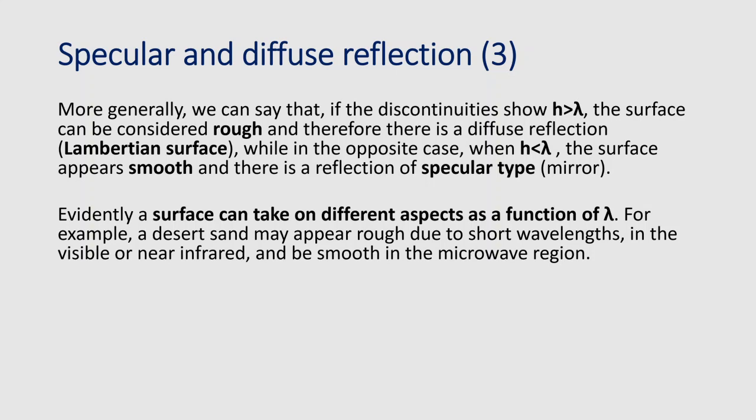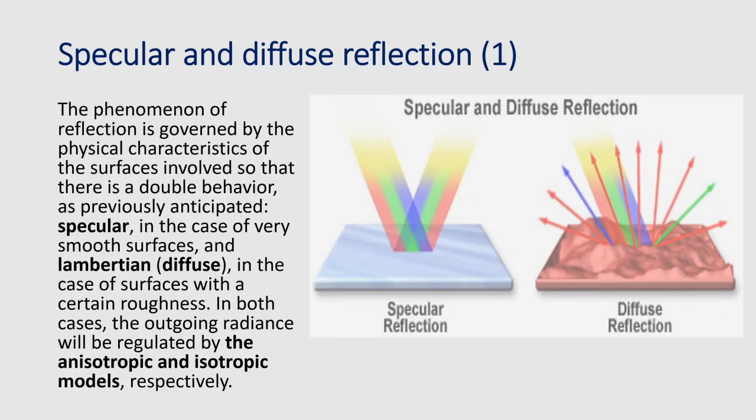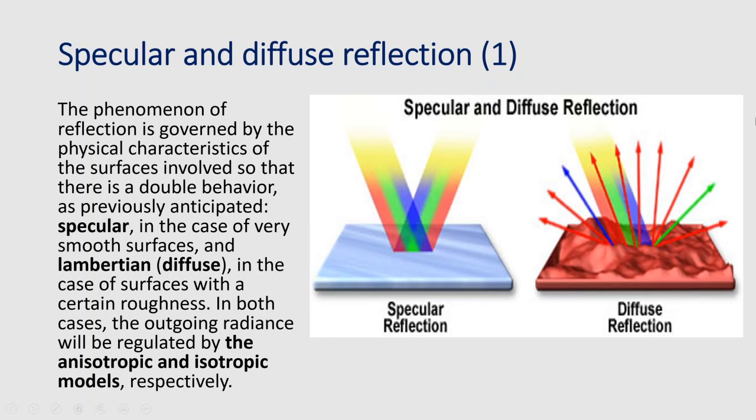I'm going back some slides, we are here. So we are in this red case here. Look at the mouse. If the satellite is perpendicular to the surface, independently from the incident angle of the energy coming from the sun, if this rough surface is reflecting energy, that means that the rho coefficient is more than 0, and part of this energy will go straight to the sensor and, if enough in terms of power, will be registered on board of the satellite.